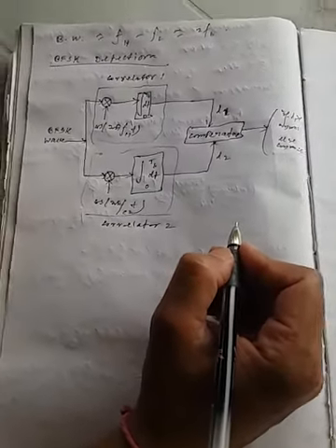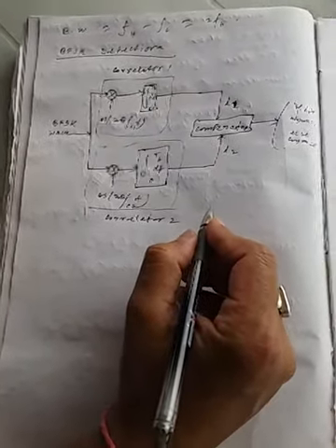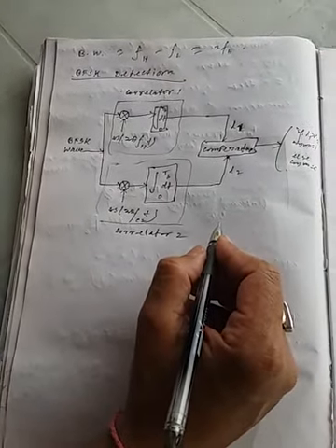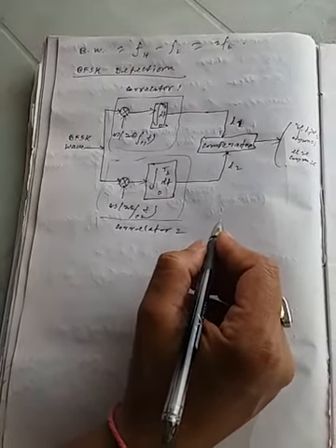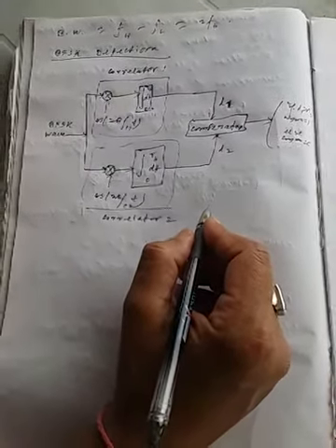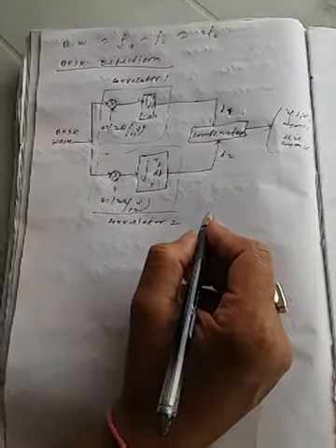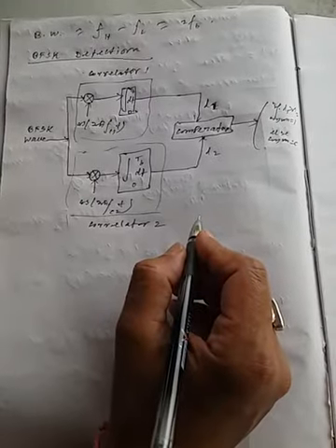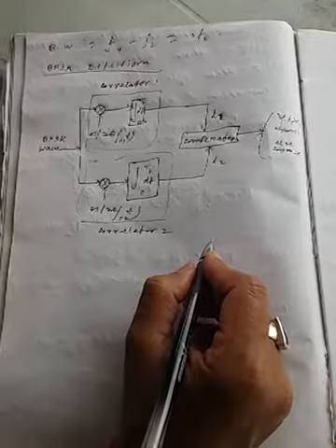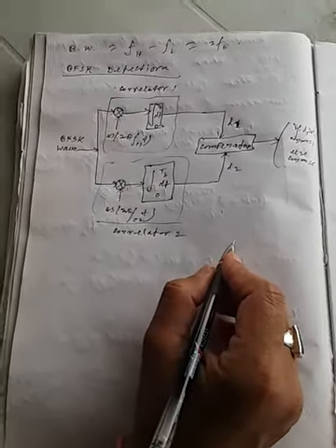A correlator consists of a multiplier followed by an integrator. The received binary FSK signal is applied to the multipliers of both the correlators. To the other input of the multipliers, carriers with frequencies fc1 and fc2 are applied as shown in the figure. The multiplied output of each multiplier is subsequently passed through the integrator, generating the L1 and L2 outputs.